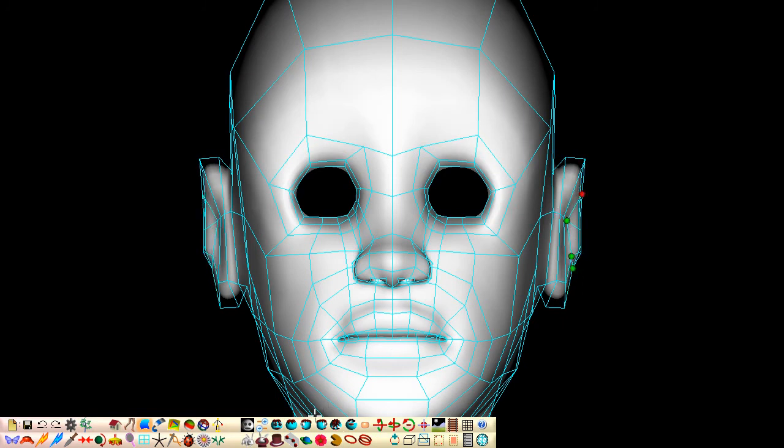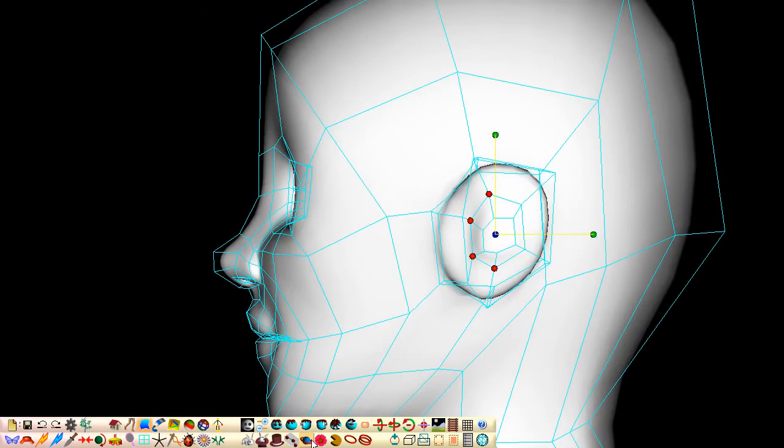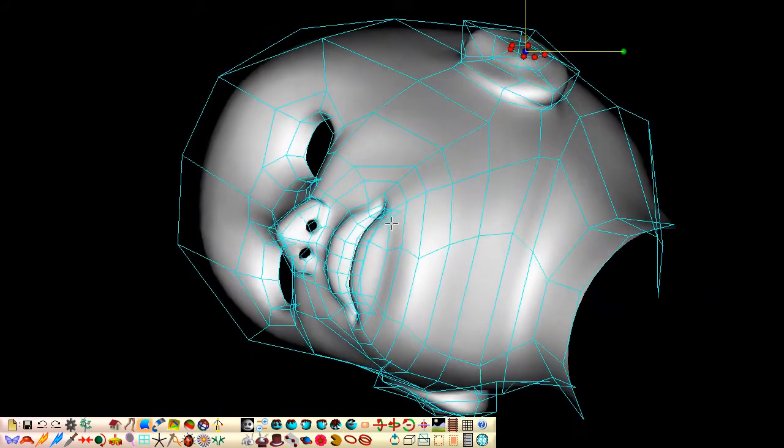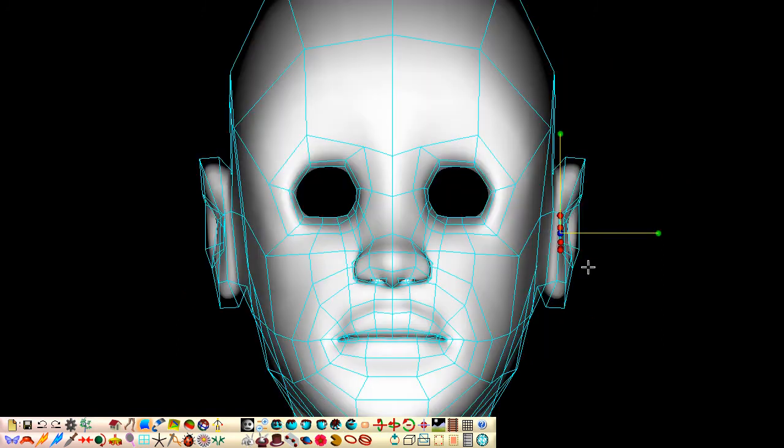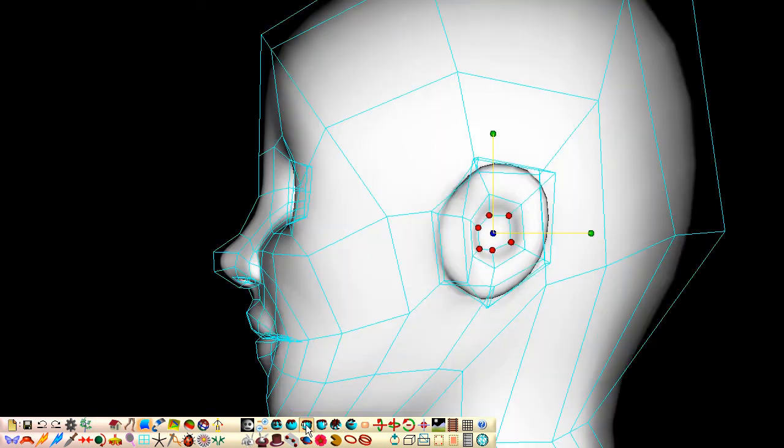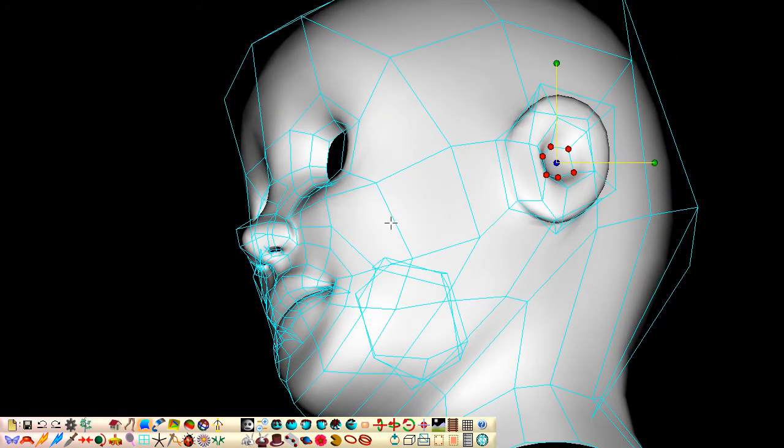Back-face ignore mode won't stop our base ring showing through our ear when looking at it from the side view, because it is in fact facing us. Some of the other rings can also partially show through when we don't want them to. This can make our work on our ears confusing. It helps to get an understanding of which ring is which by rotating the view.